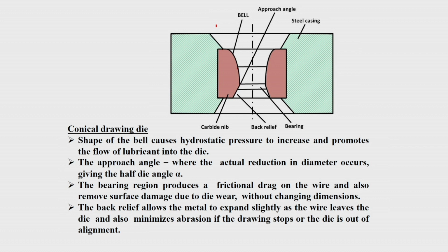But it cannot be very large. If it is very large, your drawing load has to be very large, because your total contact area will be very high. So there should be an optimum size for that.